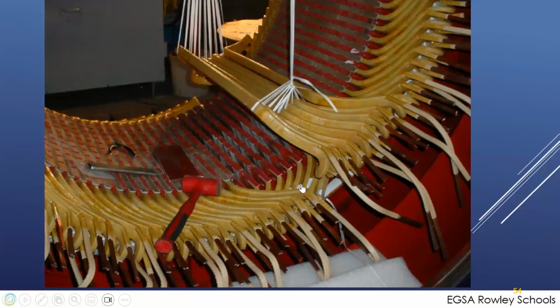These are pre-purchased form wound windings that are individually wrapped, in this case with paper, though it's all fiberglass, and then varnished. They're laid into the slots, and these little bars are hammered in between them to hold them in place, and there's phase-to-phase insulation. So you can buy a form wound versus a mush wound machine. The larger ones are form wound. It's the manufacturing process, but electrically, it's the same thing.